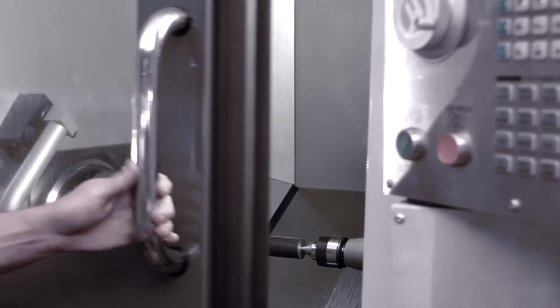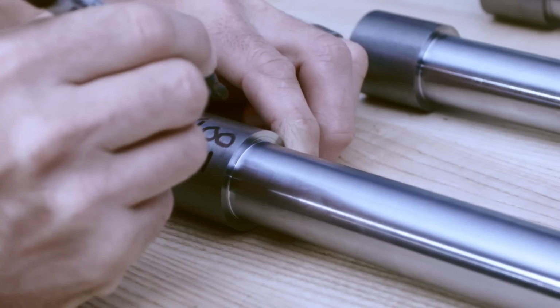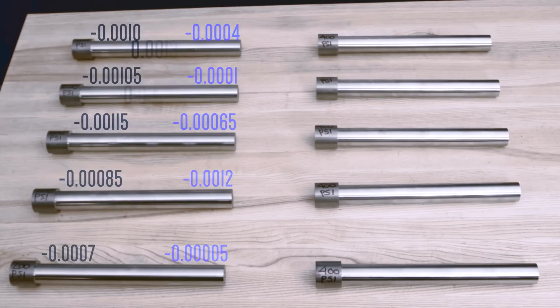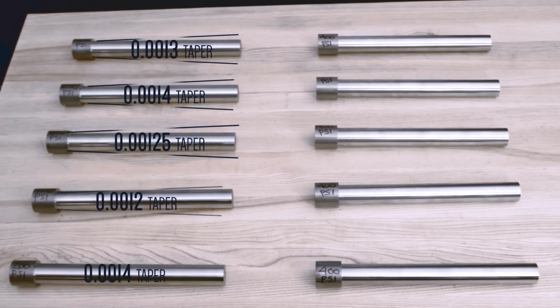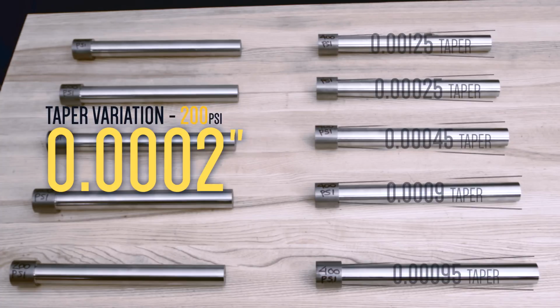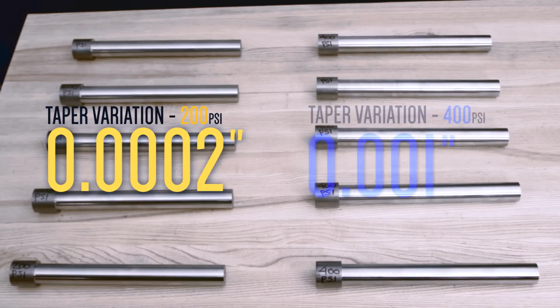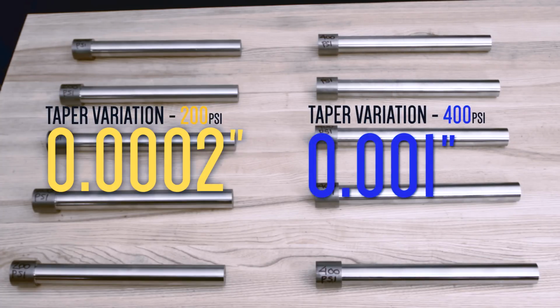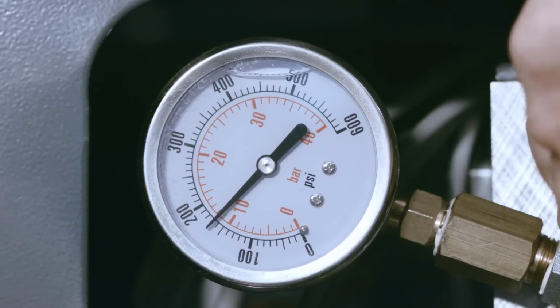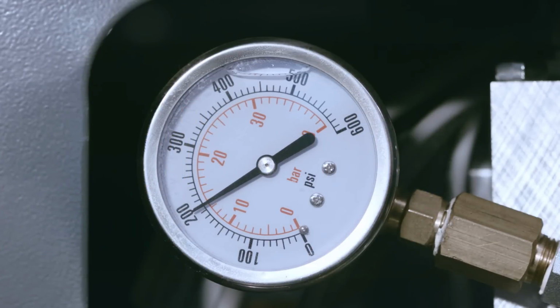Again, we cut 5 pieces at 200 psi and 5 other pieces at 400 psi using identical cutting parameters. We check diameters and find our taper values. Comparing the taper values, we find the 200 psi shafts vary by only 2/10. And finally, looking at the 400 psi shafts, surprise! The taper variation is 1 thou, 5 times greater than the 200 psi shafts. In this case, setting tailstock pressure to 200 psi gave us more consistent results.